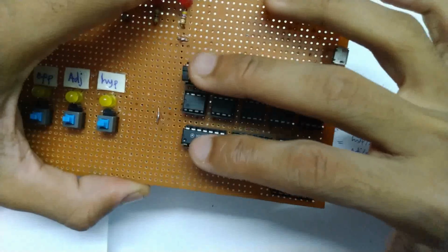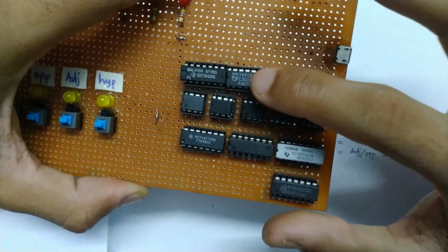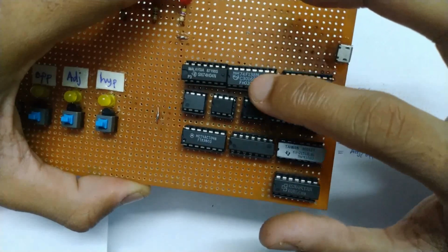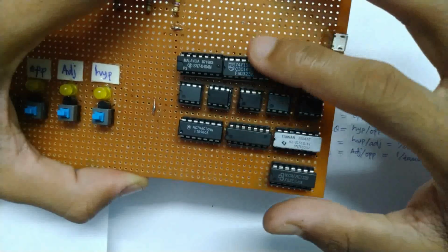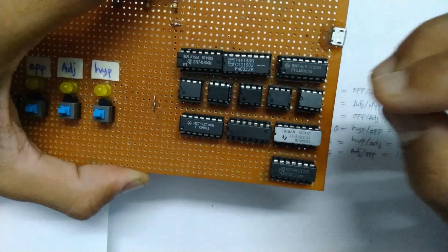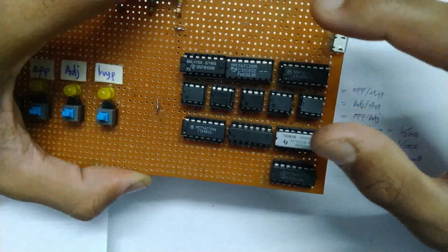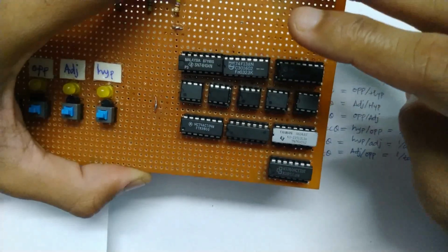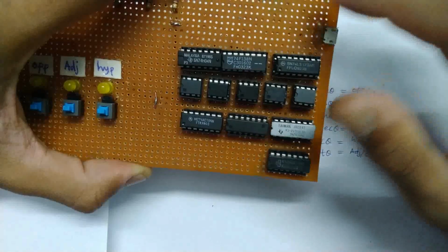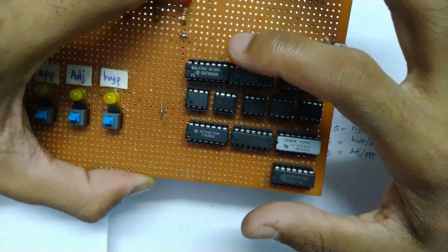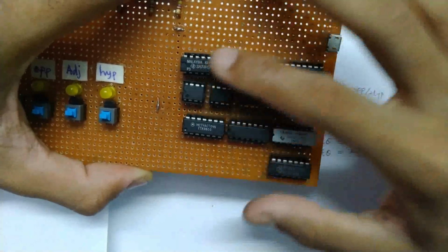So I've used 2 NOT gate ICs that are the hex inverters. It contains 6 NOT gates. The IC number is 7404. I've used a decoder, that is a general purpose 3 to 8 decoder, 74138 IC. A general purpose decoder is the one which takes in some binary value, maybe say 5 or 6 or 7, and then turns on that particular output. So it has 3 inputs and it has 8 outputs. The 3 inputs are the binary values 0 0 0, 0 0 1 up to 1 1 1, and the outputs are named from 0 to 7. So suppose I want to turn on the 7th output, I'm just going to give a binary 1 1 1 to its inputs. So that's basically how it works.